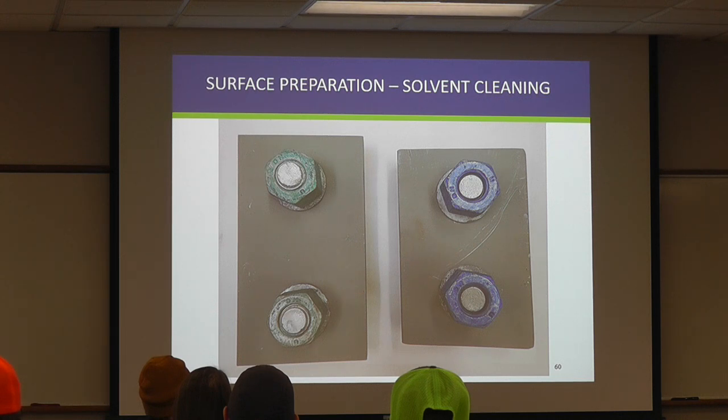we just a few years back had a bridge built in Red Wing, steel tub girders. So all your fasteners will come with these coatings on the fasteners themselves, whether they're hot dipped or it's a mechanical galvanizing, one or the other. Green's the hot dip, blue is the mechanical.